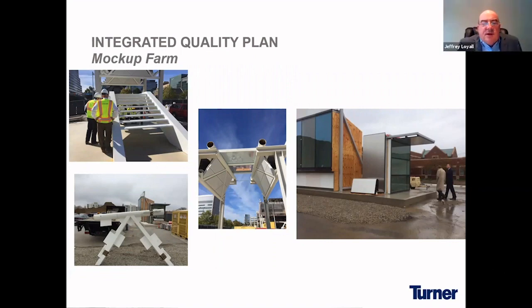Thanks, Russ. So one of the things that we like to do is have a series of mock-ups. And what you want to do is have definable features in your design that you want to, if you will, mock up, whether it's going to be an in-place mock-up like a drywall wall, or an on-site mock-up like what you see here, which are certain features that will go into the building, or a performance mock-up that Russ is going to get to in a moment. But the beauty of having a mock-up is you have a compare to, from a quality perspective.